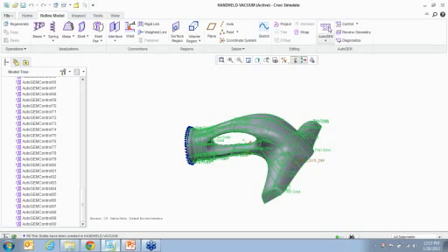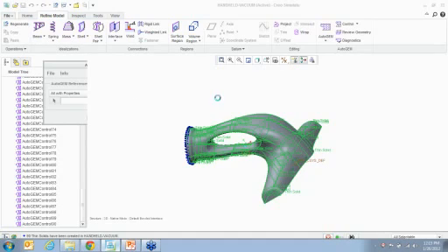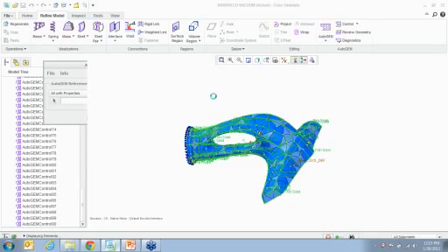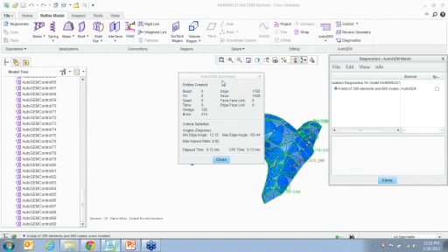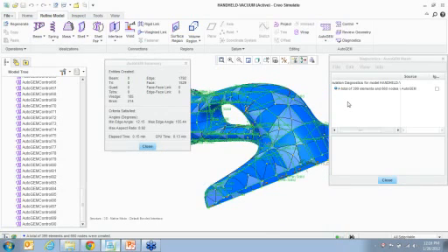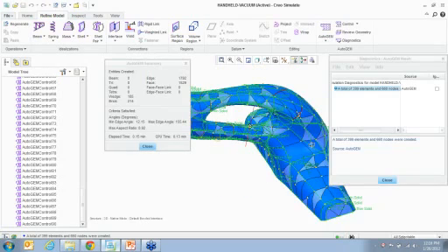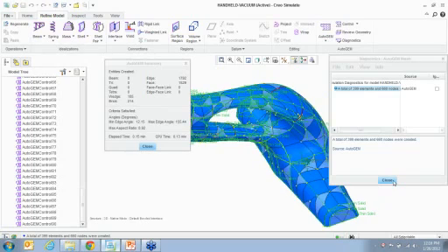So now if you go do an AutoGEM, you could see the number of elements would be around the 400 range, and the elements are much bigger, they're thinner, and it's very few compared to what we had earlier. So you can see it's 399 elements instead of having 10,000 elements. All right? So this really helps to speed up the process.